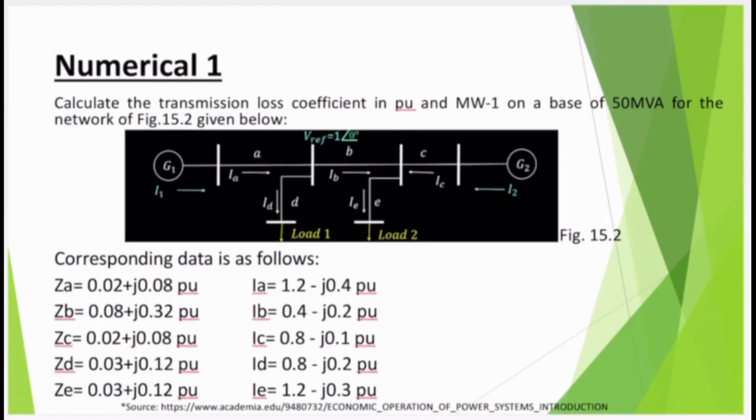It is very difficult. So that constant will be obtained as an average of all the load profiles experienced around the year, and then you can average it out to obtain all these B coefficients to be substituted in your loss formula. This is one of the numerical examples that you can check in 15.2.